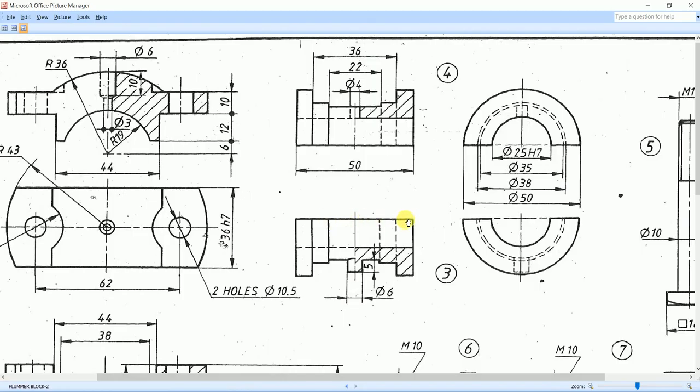This particular line corresponds to the inner circle here, and this inner dashed circle has a diameter of 35 mm. Therefore, the vertical distance from this particular point to here is 35 mm plus 5 mm additional distance we have to move down.